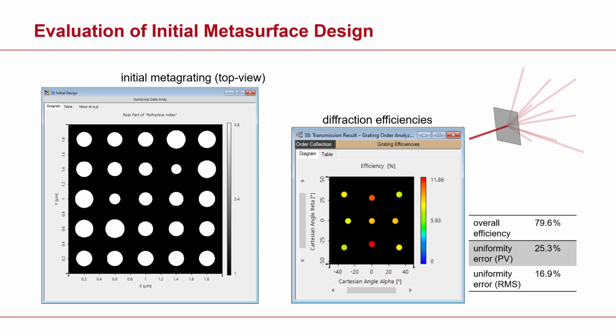This method assumes periodic conditions, so that works perfectly well both for the preliminary analysis of the regular pillar grating from which we obtain the values of the phase, and for this step where we simulate the metagrating itself with the variable arrangement of pillars inside a single period.